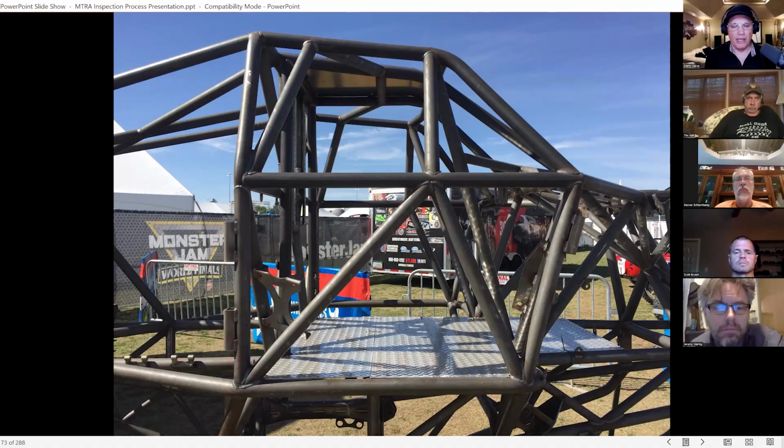You've got to be careful on how that's done, because keep in mind that a tube on end is effectively like a punch. So a really hard hit, that sharp end of the tube will punch right through another tube. That's why you don't like having T's like that. We like meeting things in corners where there's more surface area, or that there's additional gusseting to keep those things from failing. If you notice, virtually every tube you see has something behind it. It's very rarely you'll ever see a tube that just ends at one point that's not carried through.